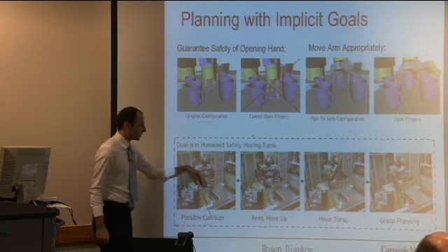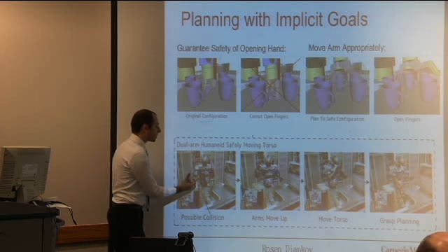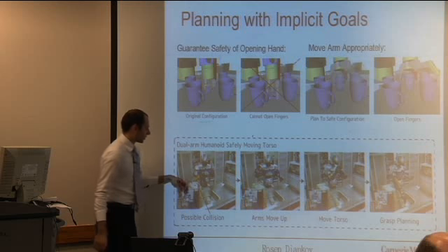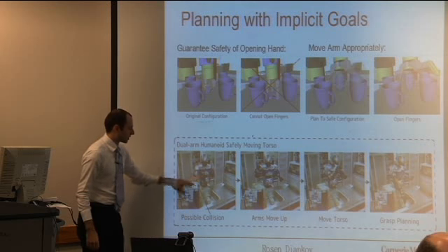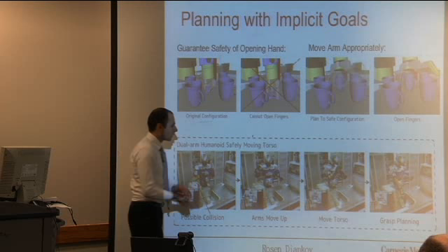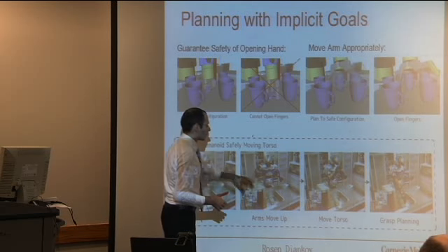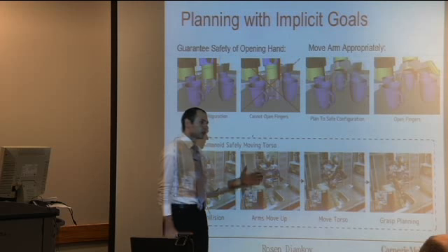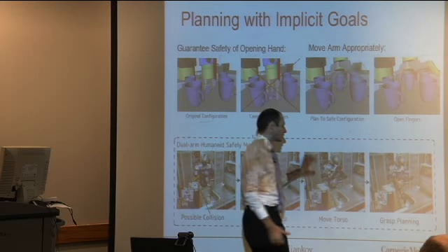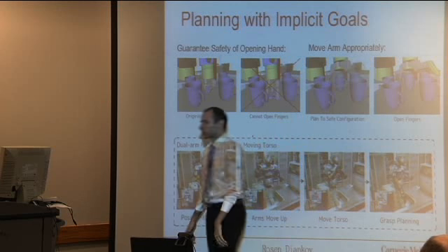And this is also very commonly used when planning with large degree of freedom robots. For example, with this robot here, we want to turn the torso of the robot to the left. However, turning it would mean that the arm would collide here with this box, and we don't want that. So using this type of planner, the robot will decide to move its hands up before it rotates. And then after it's at its goal position, you can start doing the grasp planning.